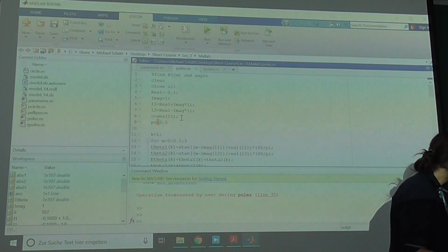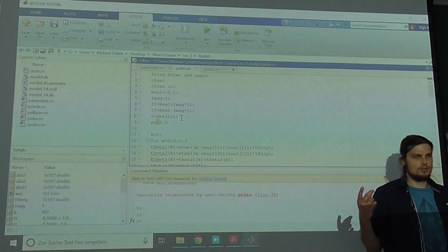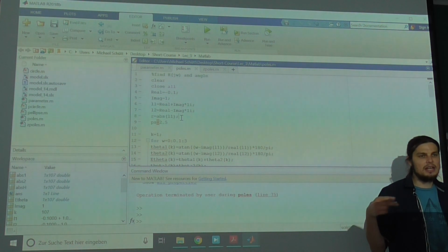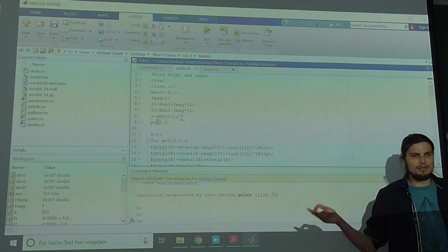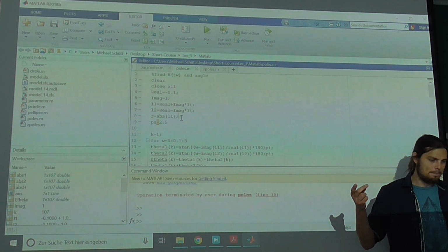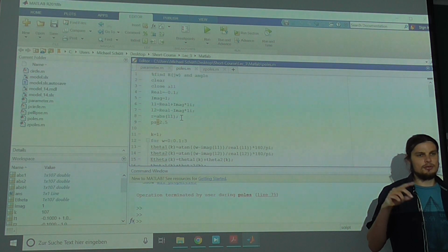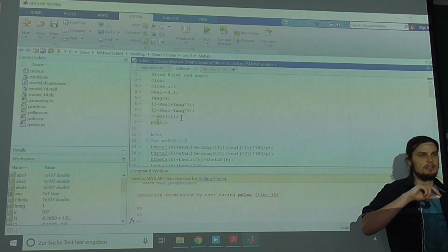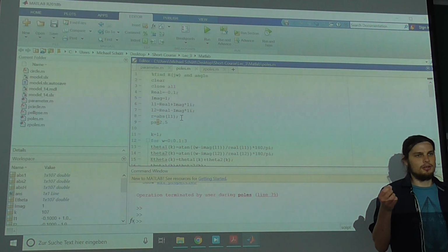Okay? And there's another thing an observer can do. It can also estimate disturbances itself, right? Because the output of the controller should be an estimate of your disturbances. Parameter sensitivity is also involved, though, right? So if you have wrong parameters, it's not just the stiffness, it's not just the disturbance, it's also information that comes from your wrong model.